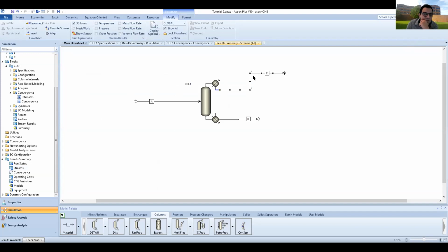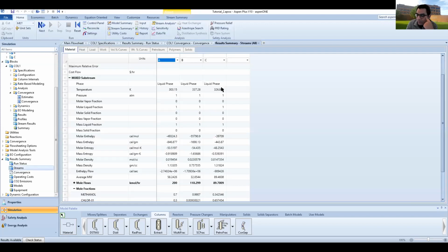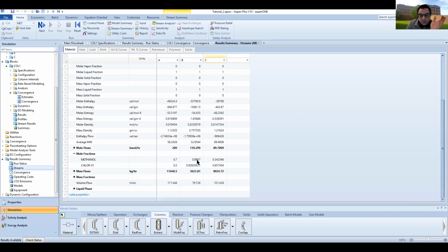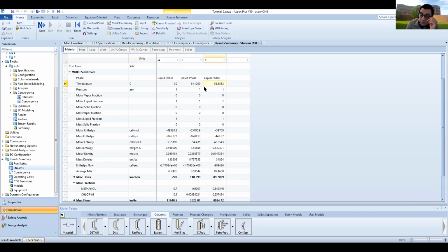is, let's have a look here. I think it was 326 something, if I remember when we were looking, so it should be about 50, right? So 326, and it's given in Kelvin here. You can always change the units by clicking, and the temperature here is 53. So to answer question number 6, the composition of methanol is 0.99. The temperature of the azeotrope, which is what's leaving from the top, is 53.6. Okay.